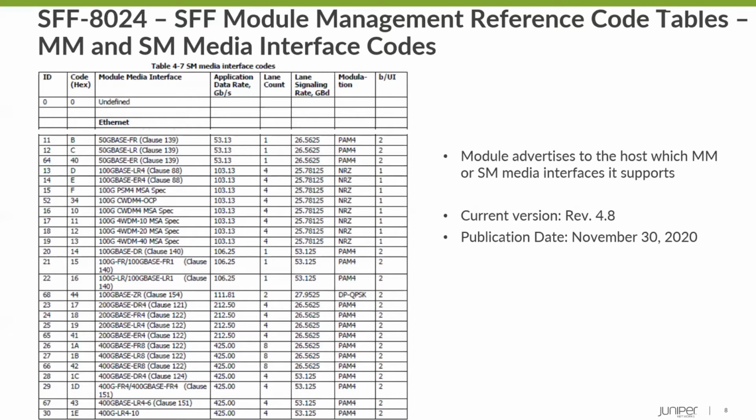Of course, sometimes there's only one application, and sometimes there's more than one. And we see in this list, for example, 400G-DR4, somewhat close to the bottom as an example. One of the things is, if it's not in this table, you can't configure the module because the module would not be able to refer to a row in this table.